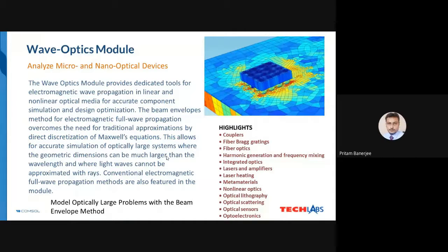It shows whether what you are trying to design is possible or not. Suppose you don't have the heat transfer module, it will not allow you to create a design where heat transfer is taken into the picture. So it will not allow those kinds of designs. If you have that module from the library, it checks whether that kind of physics is added into your license or not. If it is, you will be given the option to click the next option. Otherwise you will not be prompted with the next option.